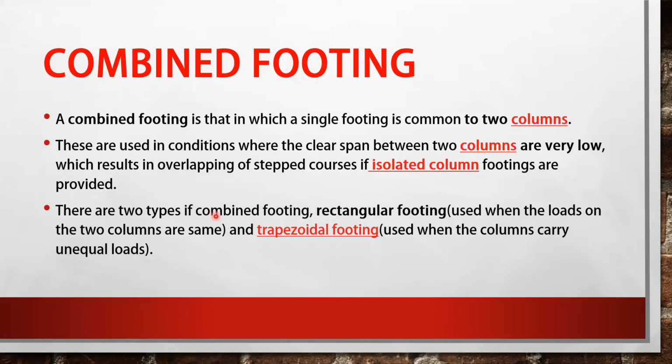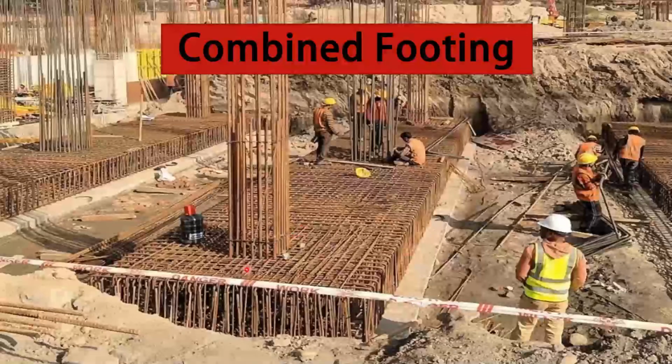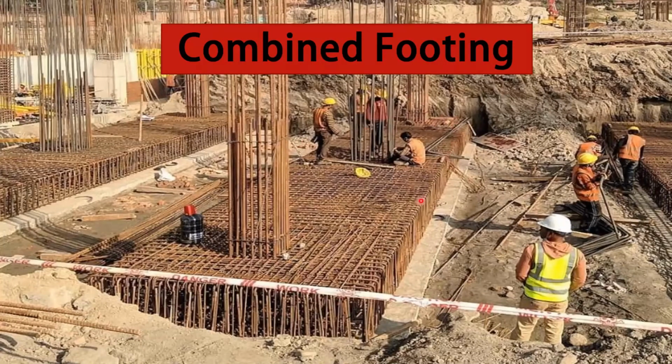And these combined footings can be categorized in two types. First one is the rectangular footing, used when the loads on the two columns are the same, and the second one is the trapezoidal footing, which can be used when the columns carry unequal loads. So you can see over here, these columns are carrying equal loads. That's why we are casting the rectangular footing over here. But suppose this column would have taken a larger load than this one, then in that case we will go for the trapezoidal type of footing. So that was all for the combined footing.